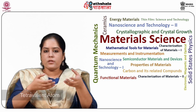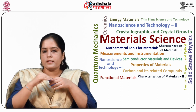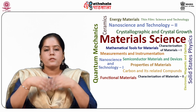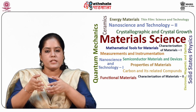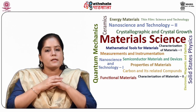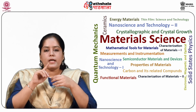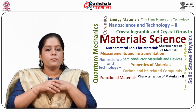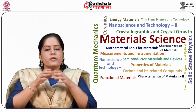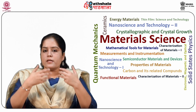Silicon, being a tetravalent atom, contains 4 electrons in its outermost shell. A pentavalent atom such as phosphorus, arsenic or antimony will replace a silicon atom and donate 1 extra electron. A trivalent atom such as aluminium, boron or gallium will act as an electron acceptor, giving rise to an extra hole.